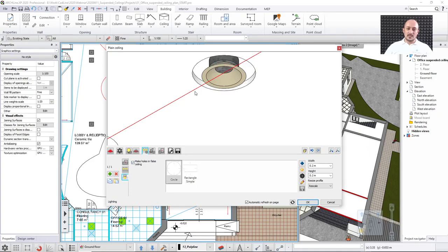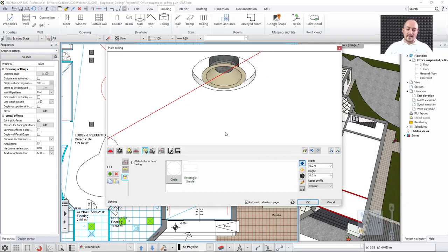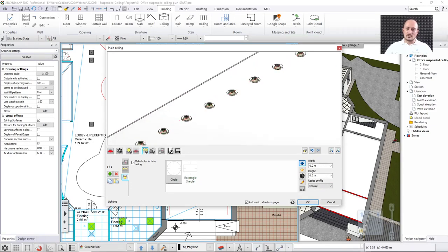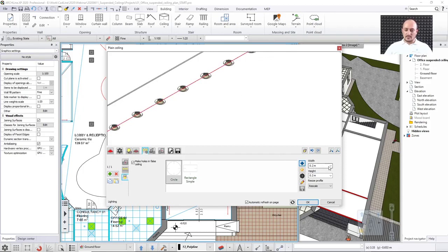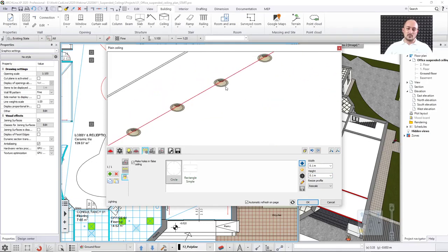This is how I can tell the software to punch holes in it, and then I pick the shape, which is much better as a circular shape instead of a rectangular one. Here I can choose whatever I want as a custom profile. And here I customize the shape because it is just too large. See, there are large holes around it, it's not cool. I just change this back to 0.1. For a fact, I already measured these, and I remember that this should be 0.1. You can just play with these values. You can type any sort of value here, or you can just measure the item and then match the size accordingly.